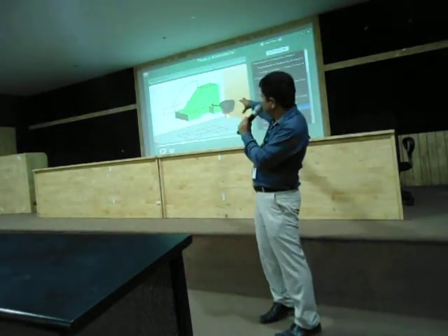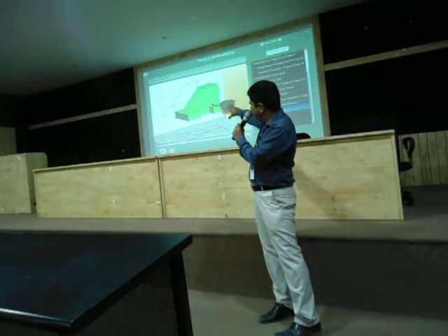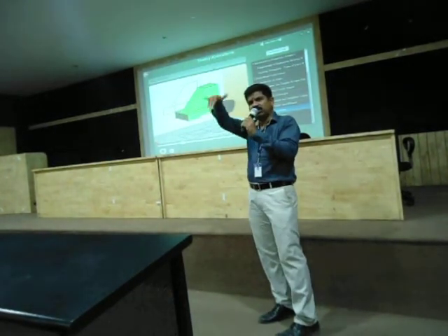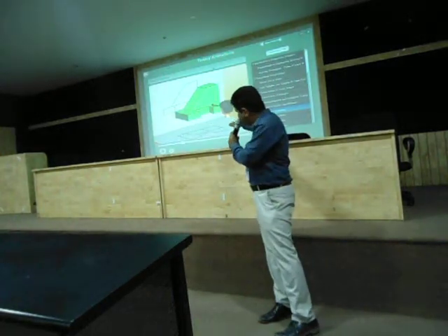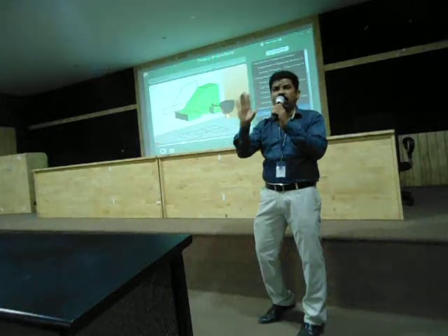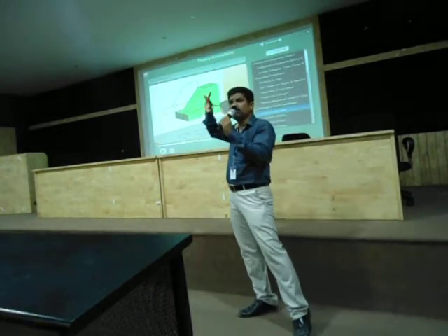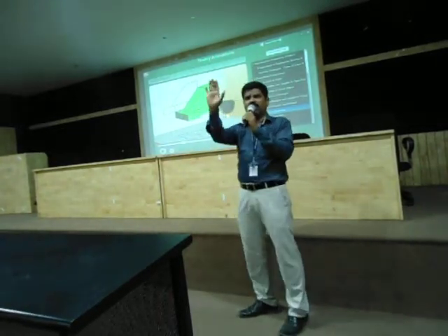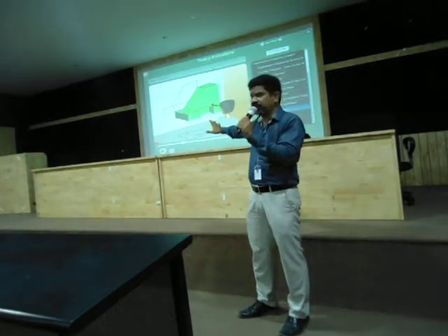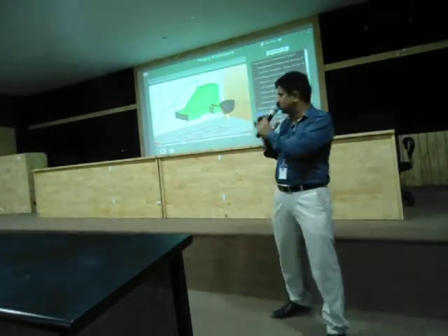So the image of that particular object is getting developed in front view on which plane? Vertical plane. At the same time, the top view image is getting developed on the horizontal plane, but as we know, HP is to be rotated 90 degrees clockwise. That's why the top view goes below XY. Front view above XY, that is on vertical plane, and top view below XY, that is on HP. So accordingly, it is shown.